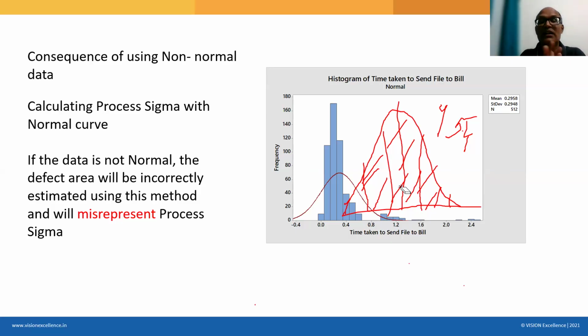Ultimately, CPK, 6 sigma, all this, the meaning of this is that you are estimating the capability of your process, right? Now how are you estimating the capability? You take a sample from a lot, and calculate with reference to that sample your standard deviation sigma.